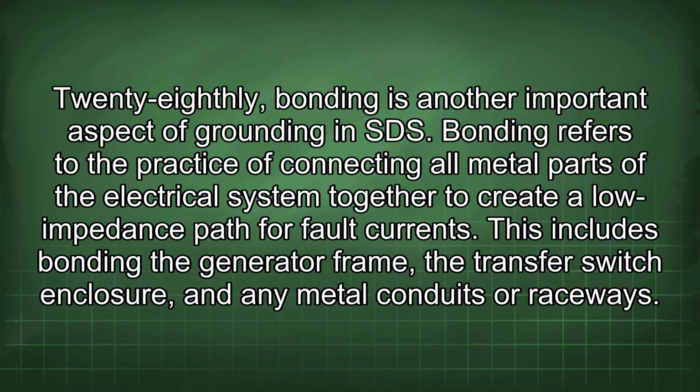28thly, bonding is another important aspect of grounding in SDS. Bonding refers to the practice of connecting all metal parts of the electrical system together to create a low impedance path for fault currents. This includes bonding the generator frame, the transfer switch enclosure, and any metal conduits or raceways.